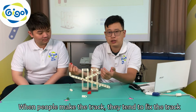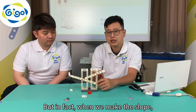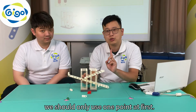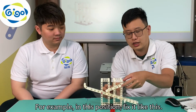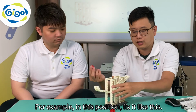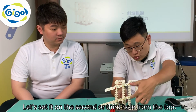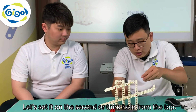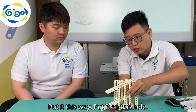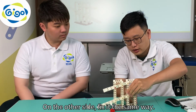When people make the track, they tend to fix the track onto the frame at the front and back. But in fact, when we make the slope, we should only use one point at first. For example, in this position, fix it like this. What about another angle? Let's set it on the second or third hole from the top. Put it this way. Put it on this hole. On the other side, fix it the same way.